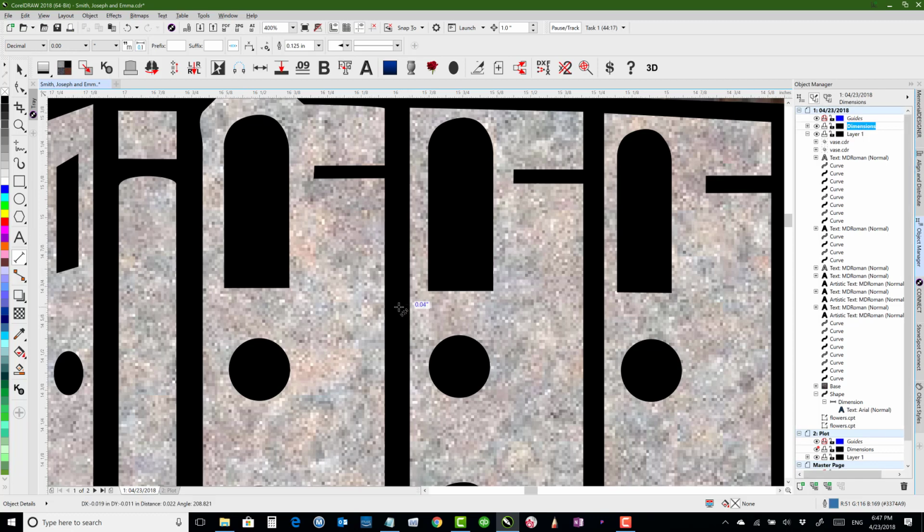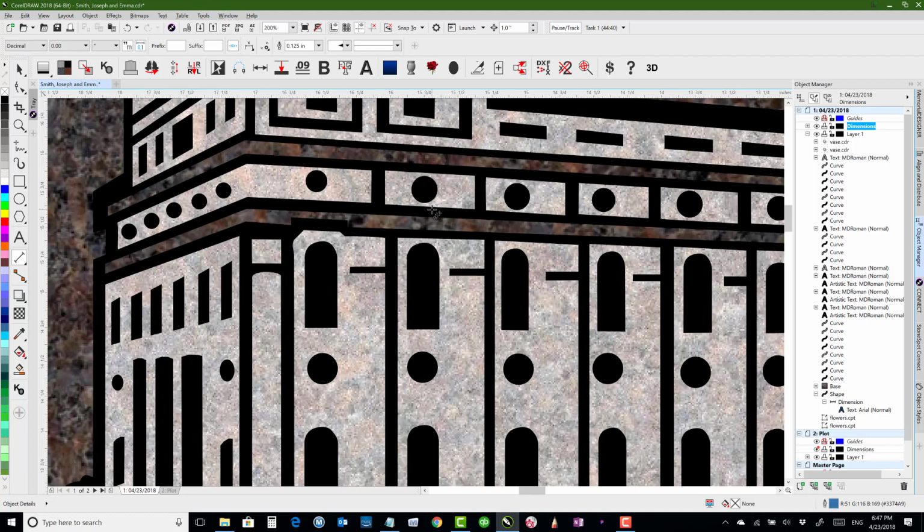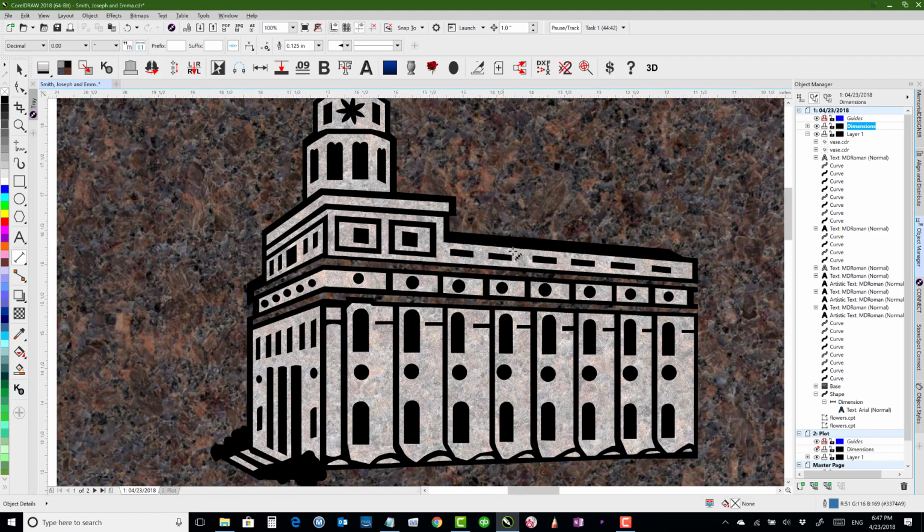Okay, so we'll click and drag, and as we do that, it actually gives us the size. So you can see it's 0.09 inches there. I can also go at a different angle, and you can see how my size grows there. But from there to there, it's actually 0.09 inches, and it's perpendicular from where I started. If I want to not make a dimension line, I just hit Escape while I'm having my mouse down, and that will then clear that out.